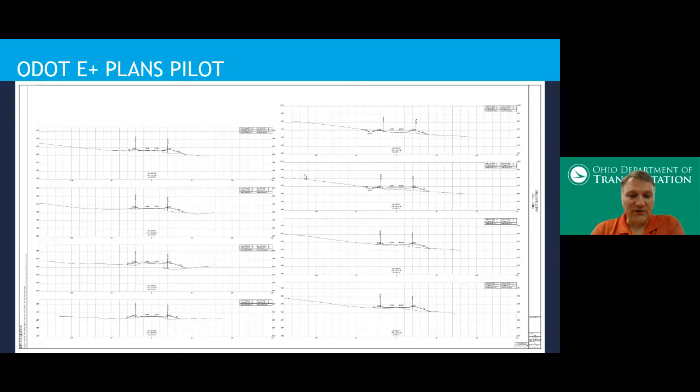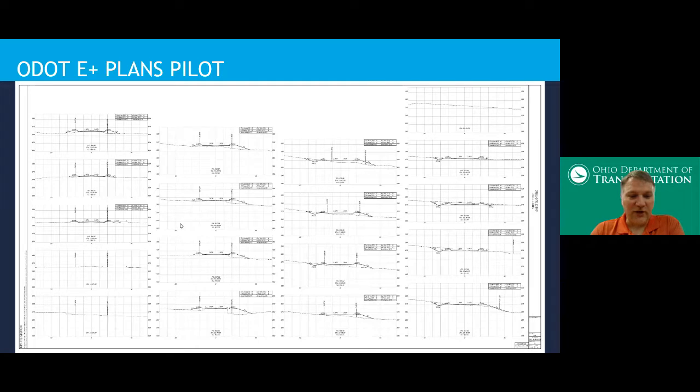And I used a small example just to show that if I want to change those offset widths, obviously that wouldn't go back to a D-size page as nicely as the original, but we can fit more sections onto one sheet if we wanted to. And go in the other direction, if you're working on an urban project or even a divided highway project and you needed to show a larger cross section, we can modify those widths when you create the drawing models to do that, so that we eliminate the need for match lines.